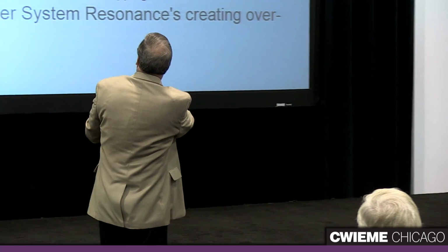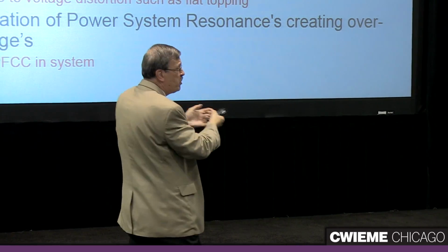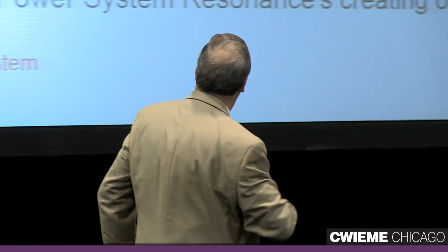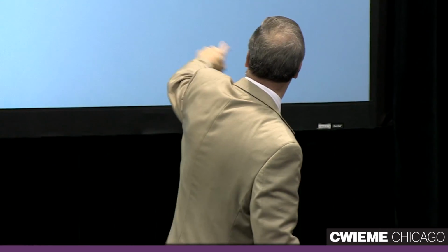Let's see, what else? You might need larger wire sizes, especially if you have a whole bunch of drives, because they have to carry more current, 10% more current. Increase in utility costs because the power factor is poor. You might get some extra zero crossings with certain types of rectifiers, not with diodes, but with an active front end you might. And power factor correction caps might have a problem with this stuff. And so then the question becomes, how much is too much?